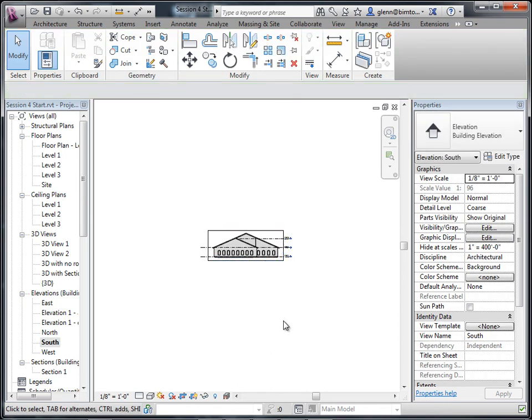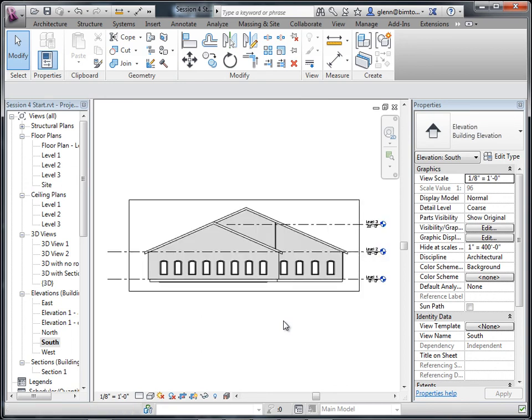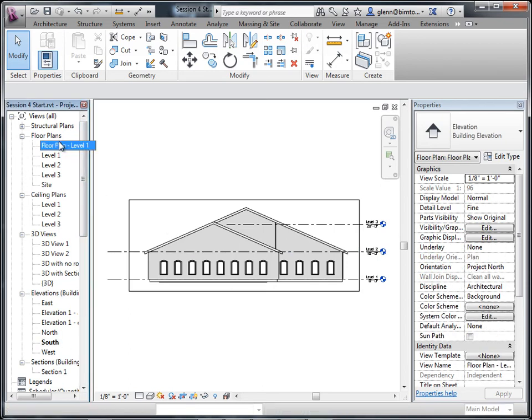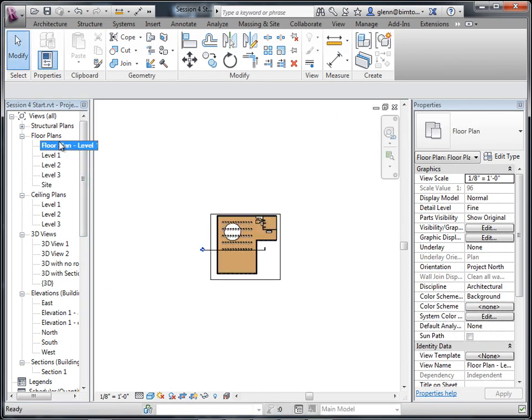As you get going, there are a couple of different things you want to pay attention to when you use this. The way I usually approach it, I like to crop the view to only show what you want to show in that specific section. For example, I have the whole floor plan for the entire space. If I want to do a detail specifically of the kitchen area and blow it up at a much higher scale so that we can really study the cabinetry and how it's going to connect together, what I might do is duplicate this view.